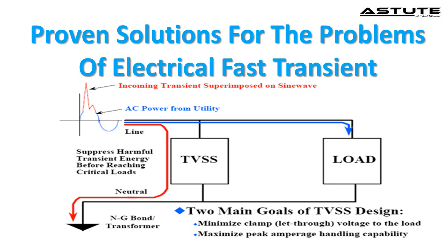The PCB layout prevents large interference voltages from appearing within the circuit. Internal circuit design is bandwidth limited wherever possible. Interfaces must be filtered or screened to a structural low impedance earth so that common mode pulses are prevented from entering the circuit. Optimize power and signal connections for transient suppression at the point of entry by keeping the wires as short as possible or by twisting supply and ground.